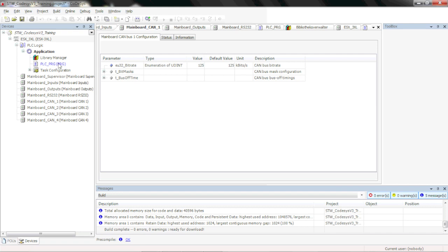Another problem is if there are multiple programs running that may be using the CAN bus, like a CAN monitor or something that's actively on the bus that might be interfering with the messages, or taking up one of the networks that you're trying to communicate on with the CAN dongle.